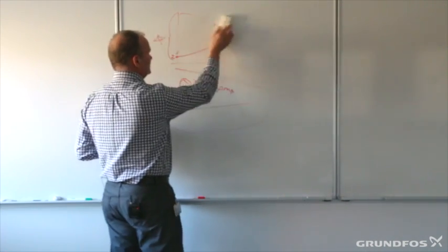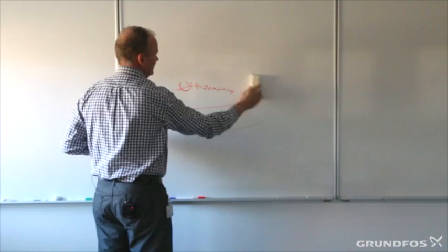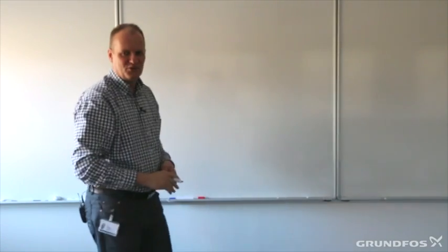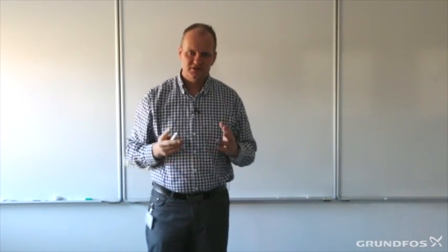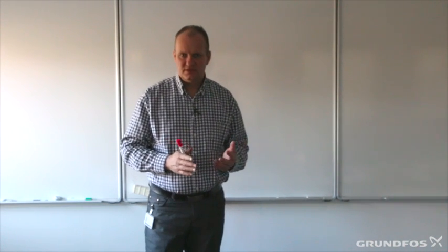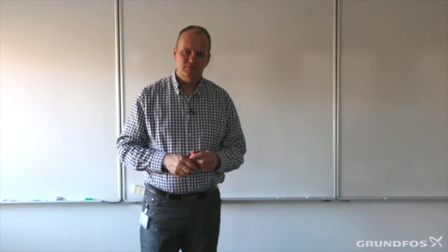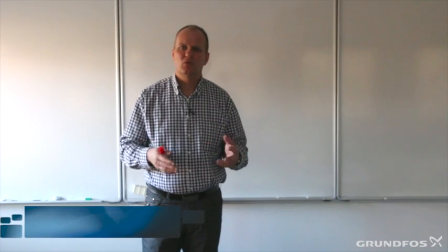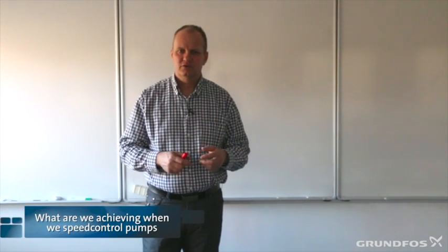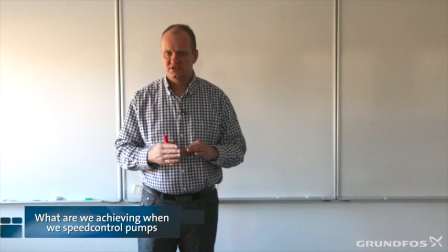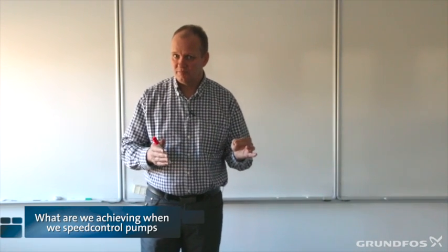We will end this session by focusing a little bit on that, and I think that's where we nail why it's so important that we focus on this speed control of pumps. So when we speed control pumps, there is a way to explain what we are achieving, or what is happening in terms of delta P and power consumption, etc., while we are speed controlling pumps.